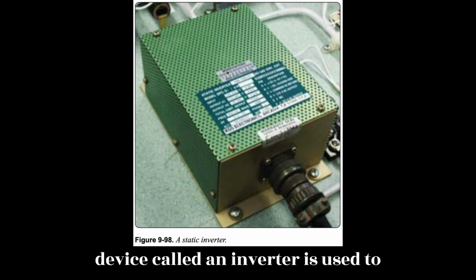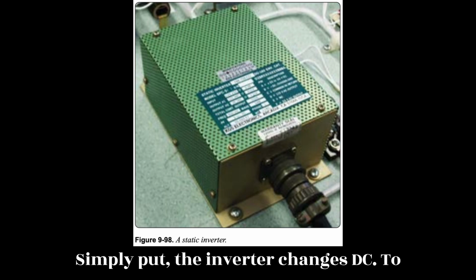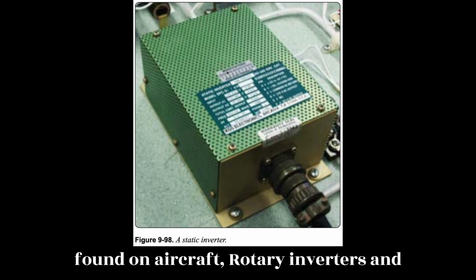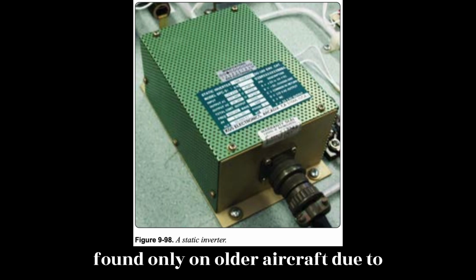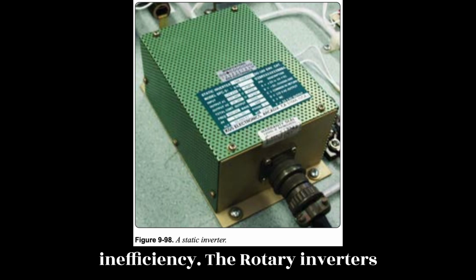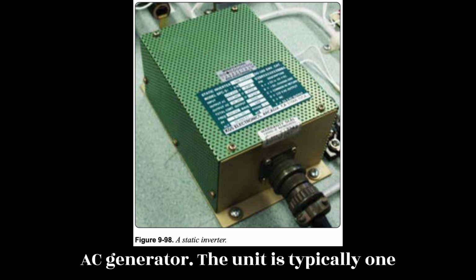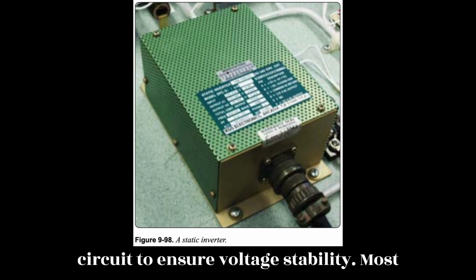A device called an inverter is used to supply AC when needed for light aircraft. Simply put, the inverter changes DC into AC. Two types of inverters may be found on aircraft: rotary inverters and static inverters. Rotary inverters are found only on older aircraft due to their poor reliability, excess weight, and inefficiency. The rotary inverters employ a DC motor that spins an AC generator. The unit is typically one unit and contains a voltage regulator circuit to ensure voltage stability.